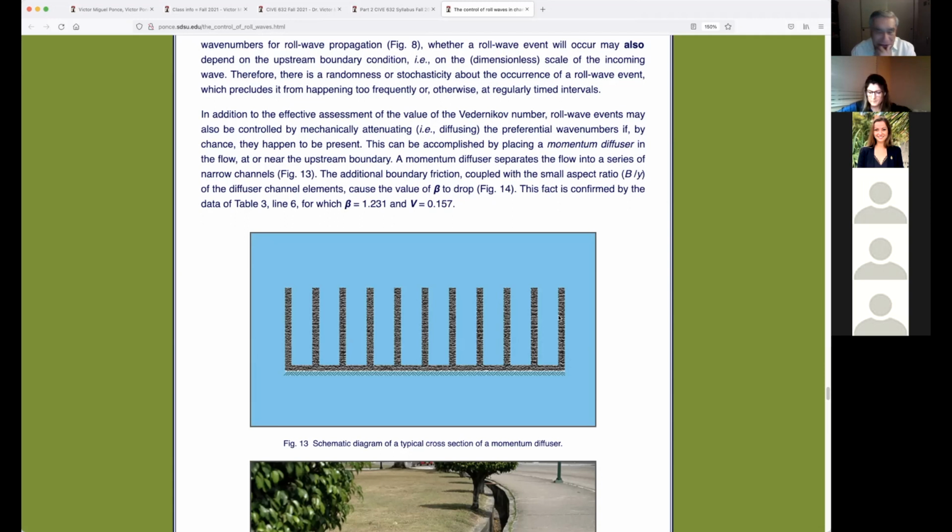By the way, a diffuser is not a new concept because it is used, for instance, in overfalls. They have diffusers at the end because they want to help the diffusion. The diffusion is natural, but it's slow. So we want to help the diffusion, particularly when you throw stuff in the ocean. All those structures have diffusers of some kind. And of course, diffusers could be diffusers of mass, or of momentum or energy. In this case, we have diffusion of momentum, not of mass. We're not diffusing the water, we're diffusing the momentum, the unsteadiness, which is the momentum. Unsteadiness is momentum, right? So we have this.